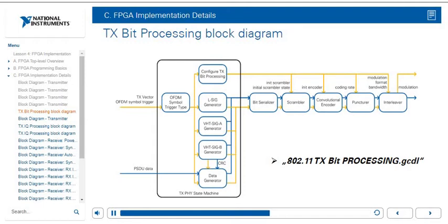After this downstream module is the bit serializer module, which converts data fields and PSDU data into 1 bit per cycle. At the start of this module, a FIFO, which we discussed earlier, is used to ensure that the module can process the incoming data rate. After bit serialization, scrambling, convolutional encoding, puncturing, and interleaving are applied. The scrambler and the encoder must be reset before the first bit of the data field is processed. A FIFO is used on the input of the module since the data rate is higher on the input. The interleaver applies the BCC interleaver operations to conclude this module.